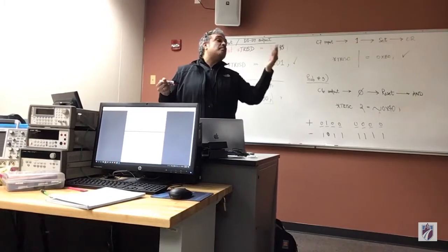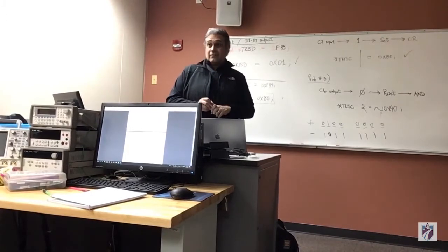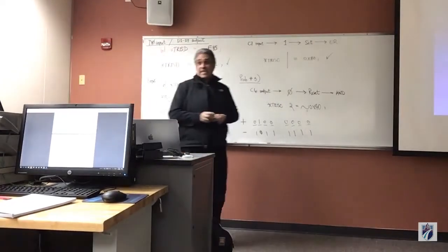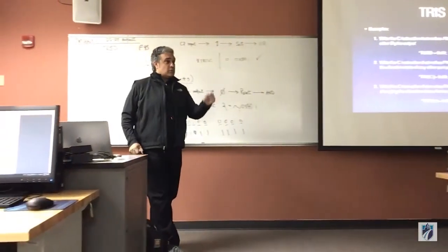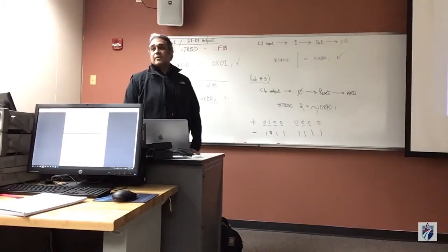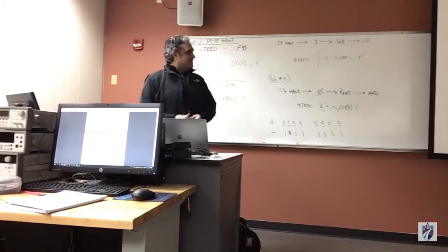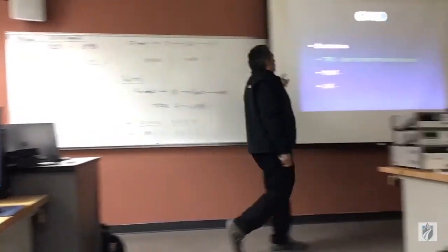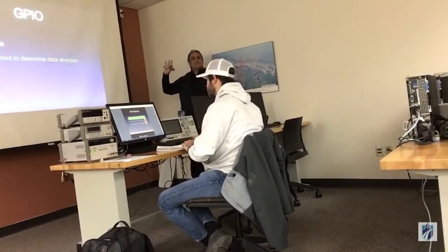Usually, 99.99% of the time, in the real world, nobody will toggle just for the sake of toggling an I/O pin. Usually you want to know the actual state you're going to be in, because it's not like turning on an LED just by chance. You want to make sure that you know that value. So I have never used a toggle for a tri-state ever in my career. I will never say never because there's always an opportunity down the road to do something crazy. But, make sense? All right. Okay, so tri-state is used to determine data direction. That's all we need to remember. That's the important part to remember.